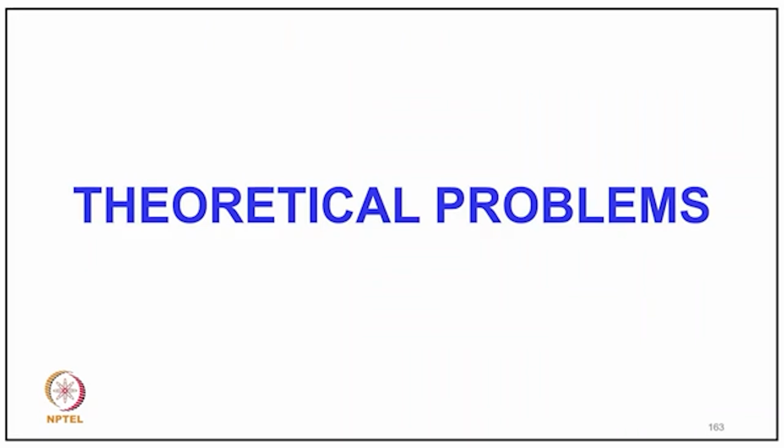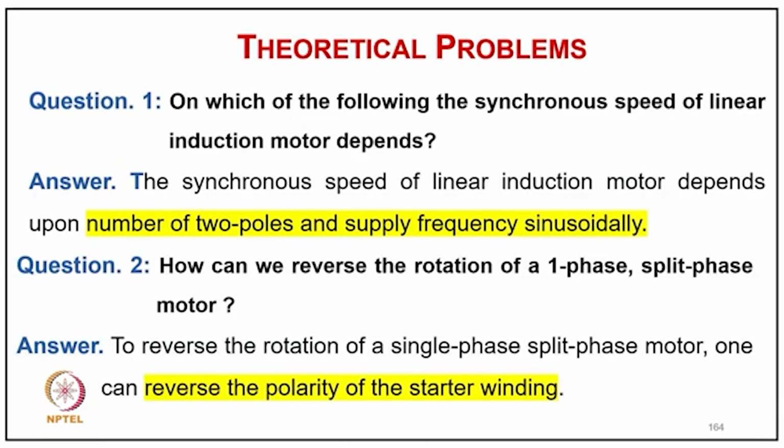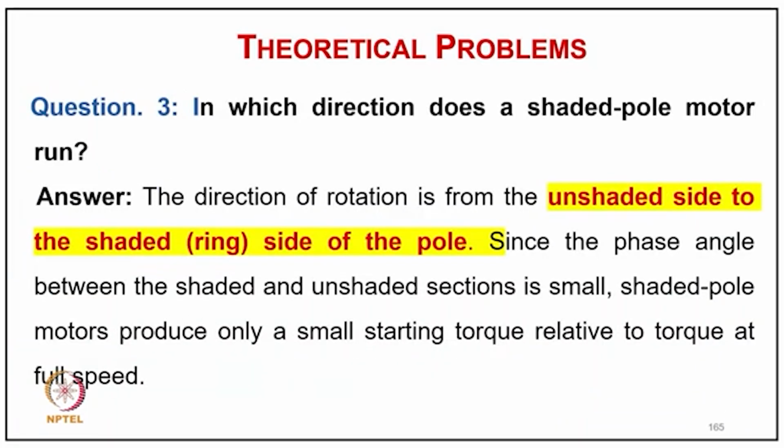Now coming to the theoretical problems. Question 1: on which of the following is the synchronous speed of a linear induction motor dependent? The synchronous speed of a linear induction motor depends upon the number of poles and supply frequency. How can you reverse the rotation of a single phase split phase motor? To reverse the rotation of a single phase motor, one can reverse the polarity of the starting winding or the auxiliary winding,